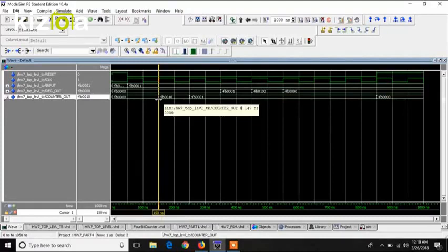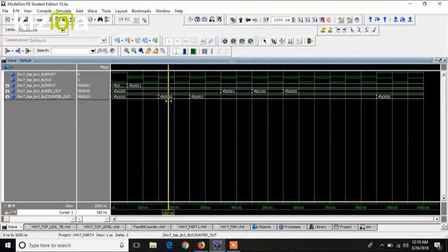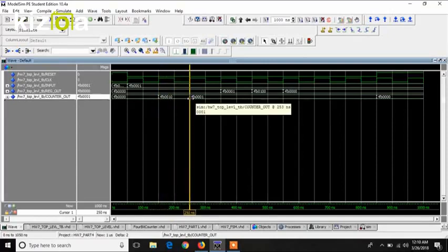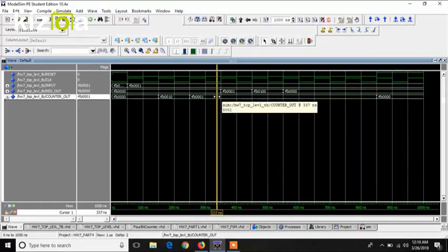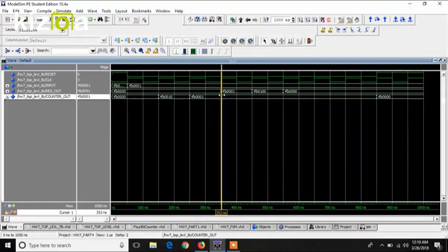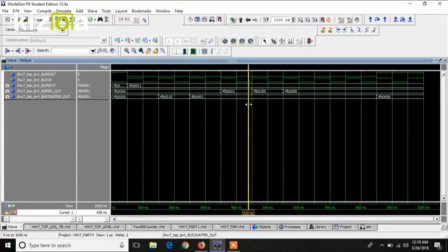And then at the next clock edge, it's going to add by 2 here, and it's going to subtract by 1 at the next clock edge. So that is what it does. And then at state 3, it's supposed to load in that input value into the register output. And there it is. And then at the last state, state 4, it's supposed to shift the bits to the left twice. And that is what it does.